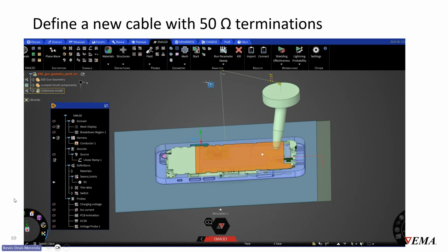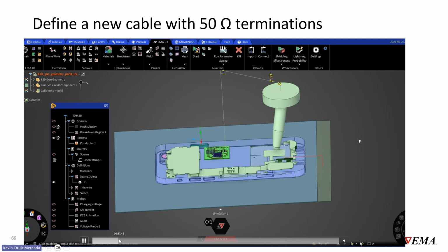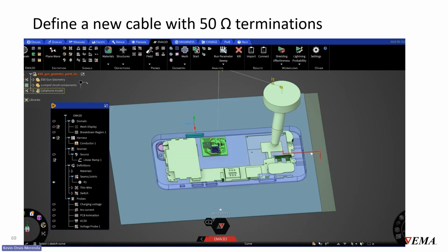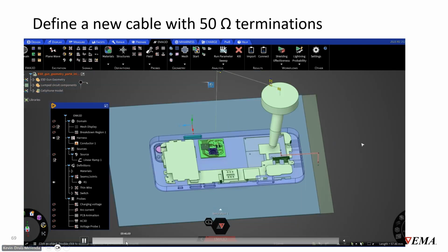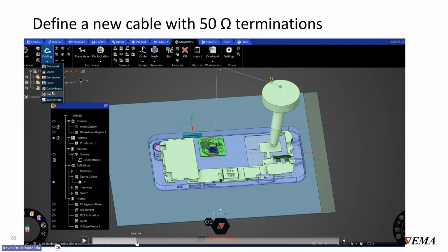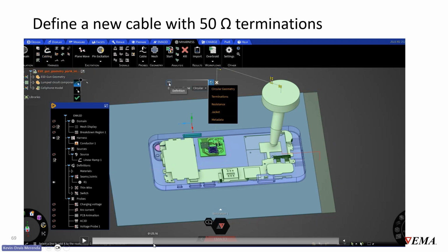And we can exchange the current and voltages at the end of the conductor with the circuit solver to be able to place a component much more complex than the linear components that we typically use for thin wires at the end of the wire. So here we're actually looking at how to set up the conductor.